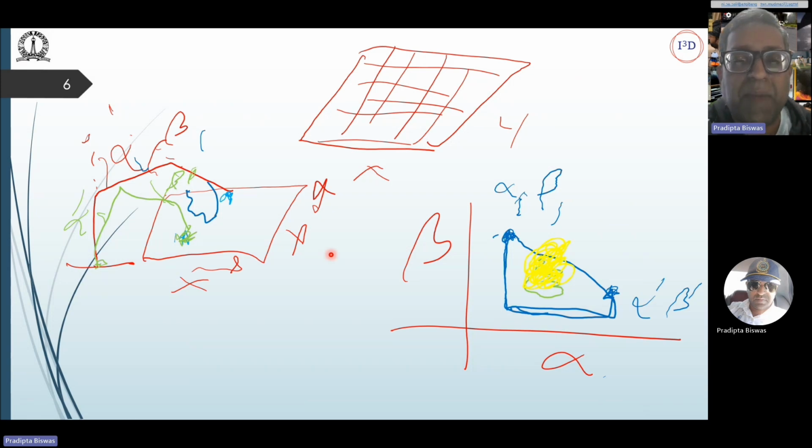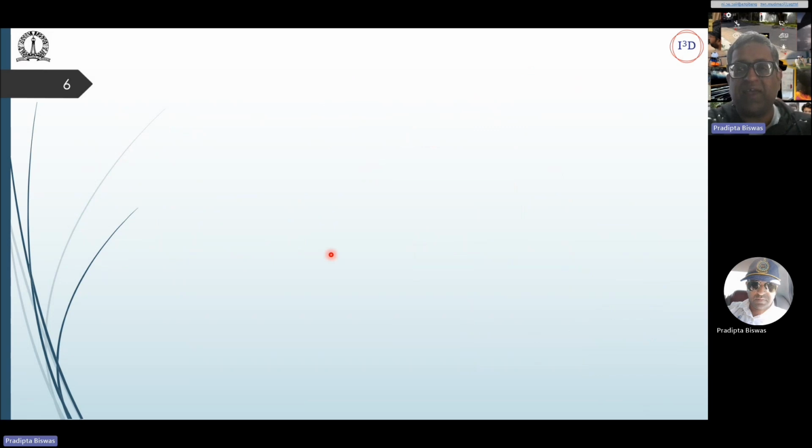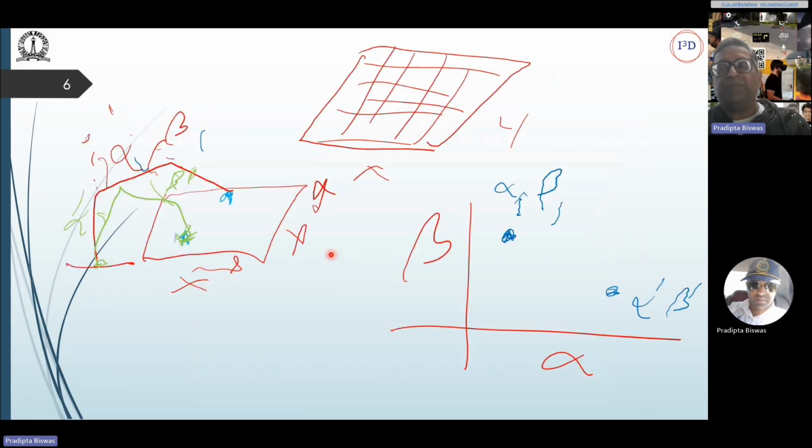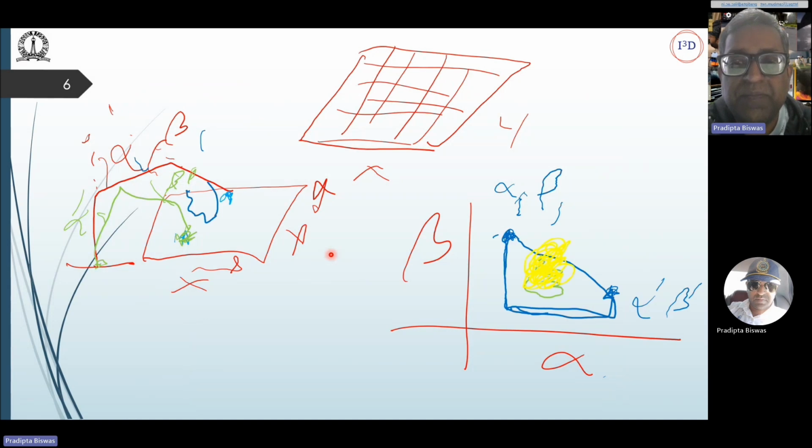But the problem there is mapping these joint angles to the robot workspace, as we did in the previous slide. That is our kinematics problem, or forward kinematics problem, and that is often easily solvable, moving from joint angles to robot workspace coordinates. But the inverse kinematics problem is sometimes more difficult, that is, converting these Euclidean XYZ coordinates to the robot's joint angle coordinates.